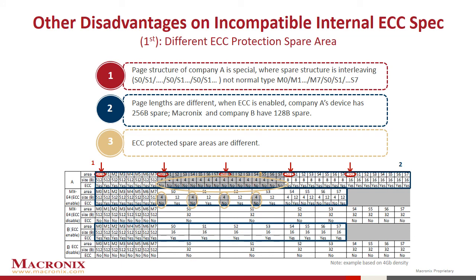So it's up to the customer to design their firmware to accommodate these differences between multiple vendors. This is an unnecessary overhead and limits the flexibility to select different NAND vendors. However, if the ECC function is performed by the host, the application firmware does not have to consider these variations from each vendor. As long as the host provides the minimum error correction needed, it can support any vendor's serial NAND device.